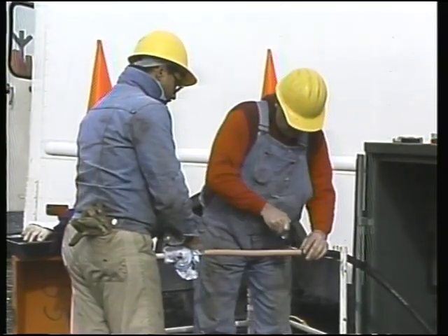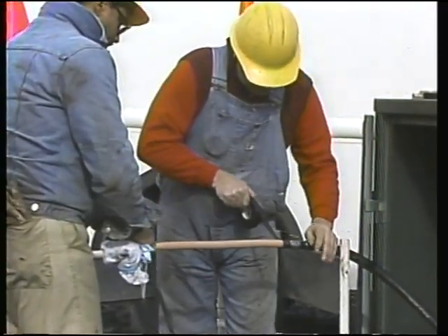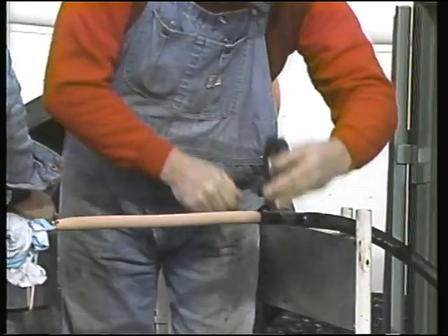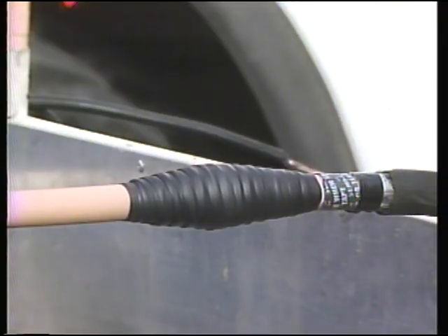The rubber insulating tape is applied starting at the insulation shield and moving toward the lug. The tape is used to build up additional insulation in the shape of a cone. The cone should be tapered evenly at each end. Its diameter at the center should be built up to the dimensions specified in the instructions. The actual size of the cone will depend on the voltage that will be applied to the cable and on the type of cable insulation.